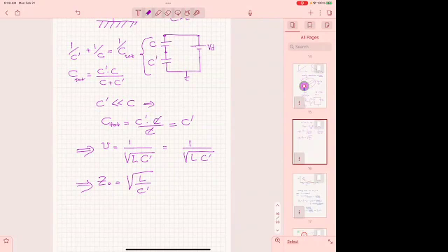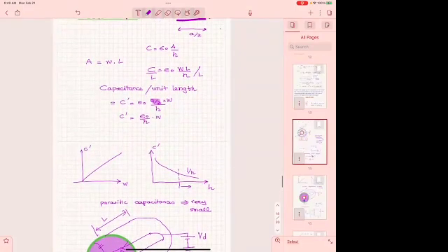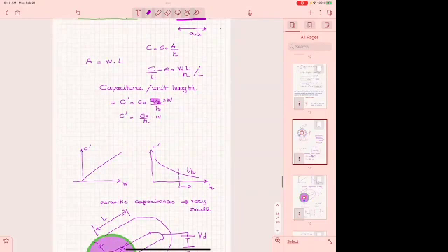Yes. L is length here, in this particular example. Yeah, L is length. Sometimes we call them coaxial waveguides. The waveguide is the old terminology for a line. We got rid of it. We use it only very specifically to make some differentiations between some types that are different than transmission lines, all right? So we use line for us at this moment. Yes.